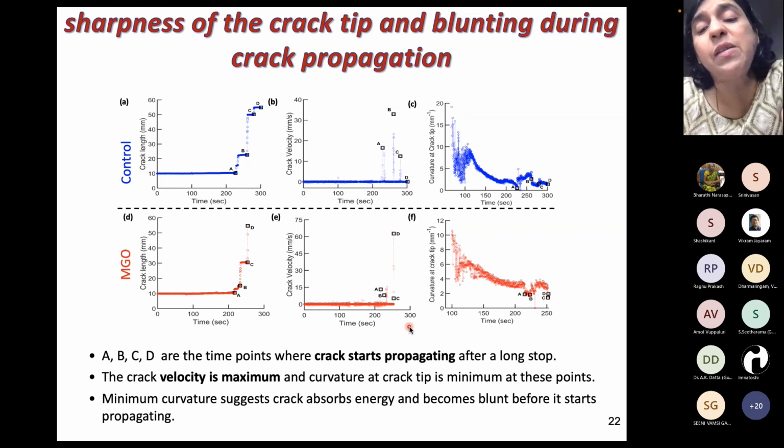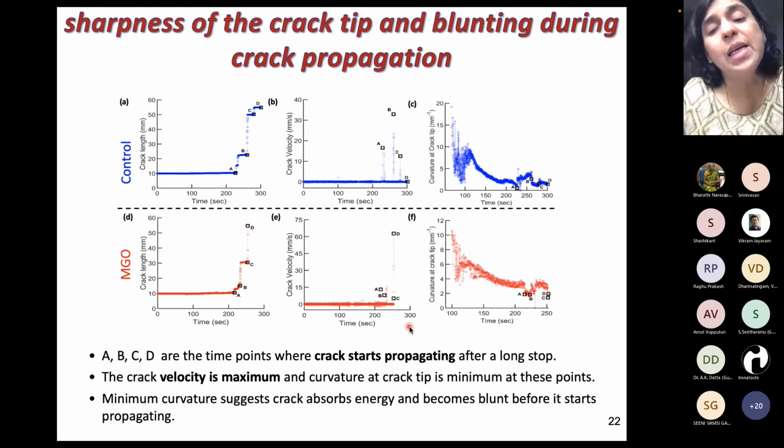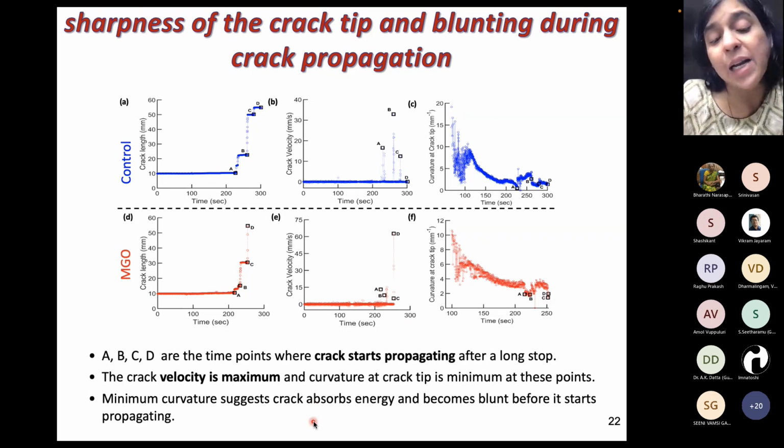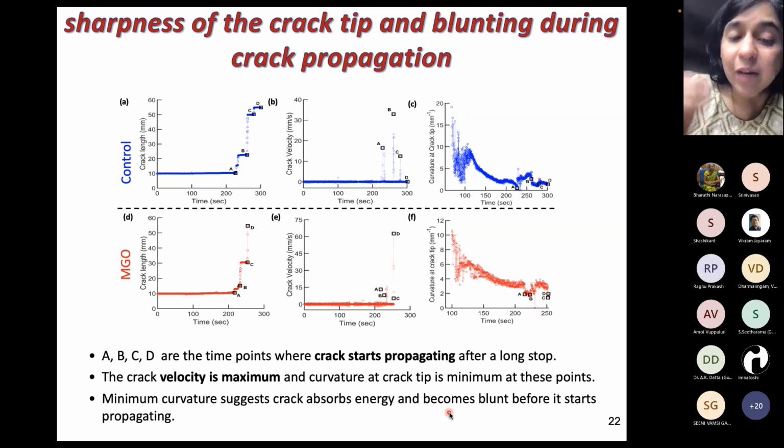where the crack propagates when it is at its sharpest points, here we have something very counterintuitive: that most of the energy that we are supplying, the mechanical energy due to stretching, seems to have been used in absorbing and blunting this crack tip. And when the crack is at its most blunt point is when it starts propagating once again.